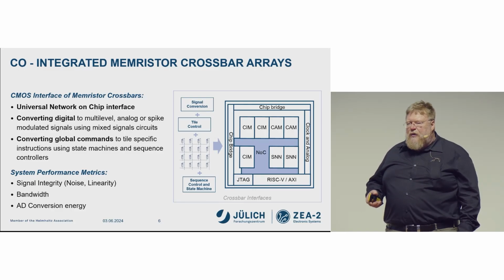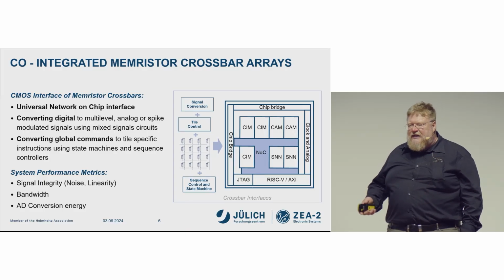On the one side, you have to connect to the central network on chip with a standard interface where you can read the data and also global commands. On the other side, you have to convert the digital signals into the appropriate signals that are used on the tile, which could be analog, could be spiked, or they could even be multi-level symbols.